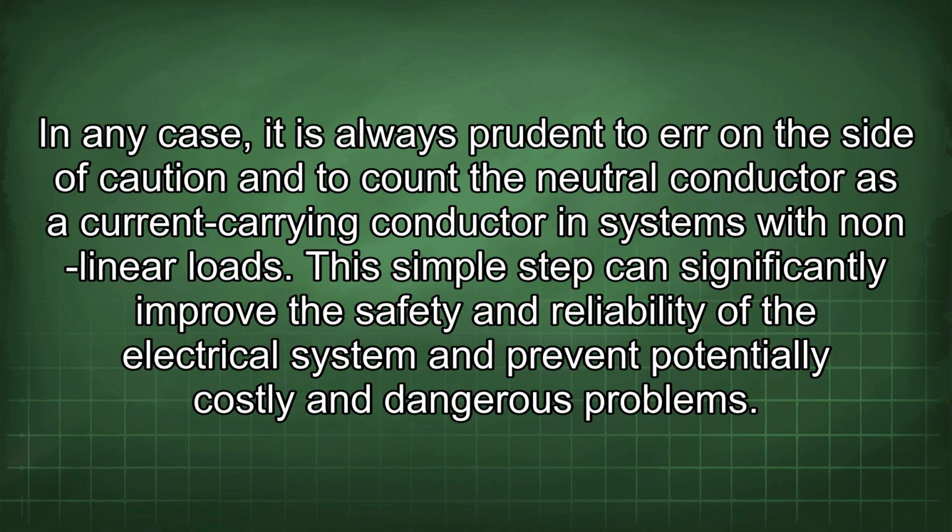In any case, it is always prudent to err on the side of caution and to count the neutral conductor as a current-carrying conductor in systems with nonlinear loads. This simple step can significantly improve the safety and reliability of the electrical system and prevent potentially costly and dangerous problems.